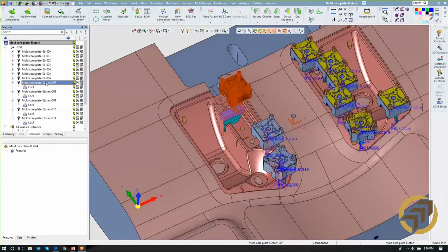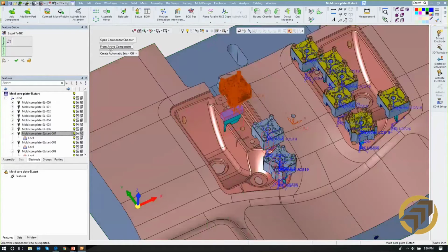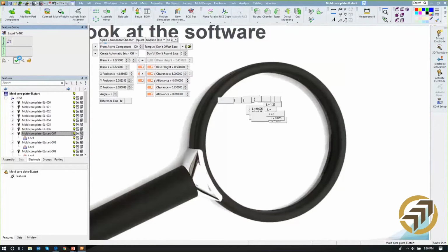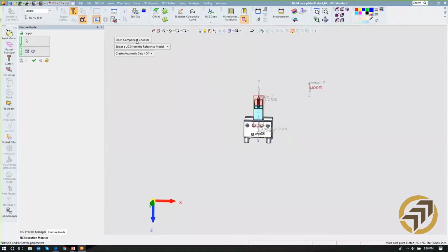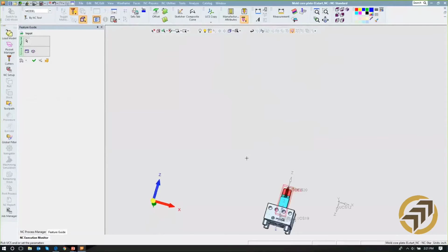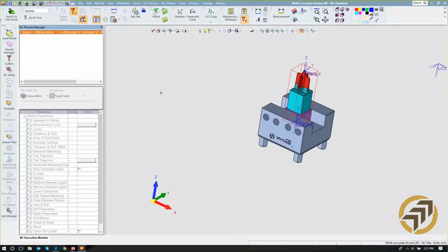With that, we'll say, okay, let's take what we got here. I'm going to work with the first one I pulled and say, let's send this over to NC. And we'll pick just that individual component that you see in red and say, okay. So a little jump right there. Now it's brought into NC, and it's asking me to pick where I want to locate. Well, remember we made that coordinate system that we said was going to be the position we'd call 0 over here on the NC table. So with that, now we brought the geometry in, got it into location. It's ready to be cut.